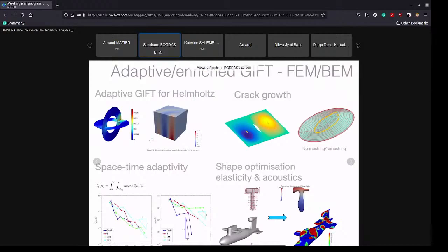If you remember, when I showed you this example, which looked like a T, which was extruded in this direction, right? And then I said, okay, next to these corners here, you may have some problems with the mesh refinement. And so then we split this into several parts. And then we said, okay, we're going to map each one to a cube. And that's going to be easier than trying to map this T to a cube because it doesn't have the right geometry. Similarly with the patch associated with this hole in the middle. If you remember, we said that each of the 4 patches needed to be mapped to a cube. That was an easier way, because otherwise you would not have the right topology. And then generating a mesh for such a topology here is not at all easy. So boundary elements really go around this, and I think it's one of the very elegant methods that can be used here.